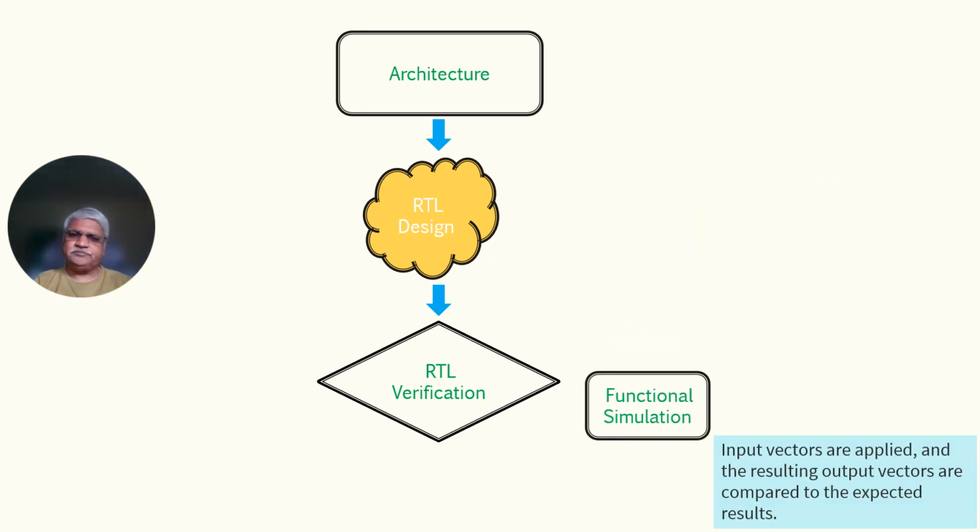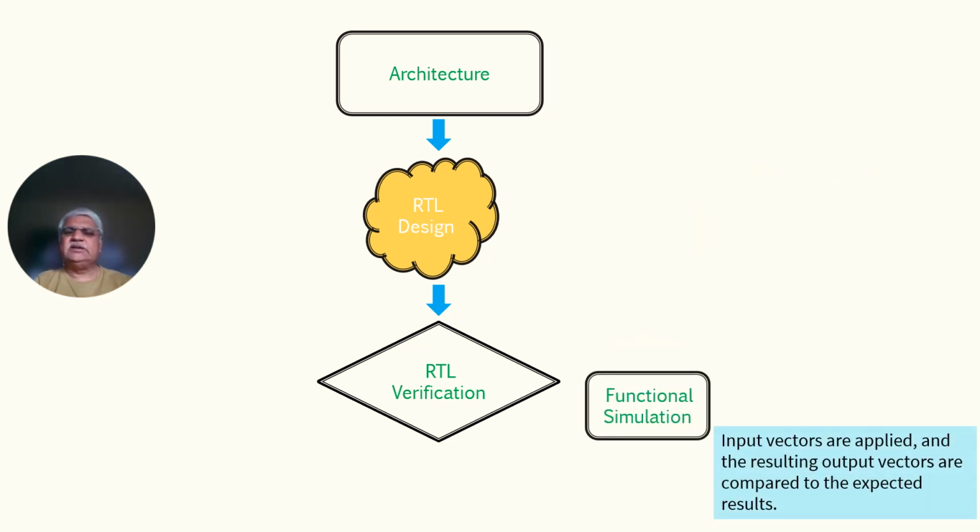If we understand this, then we will be able to implement the thing correctly through functional simulation. As part of the static verification, this is formal verification. There are EDA tools from Cadence, Synopsys, and Mentor, which model the expectations into mathematical algorithms and then evaluate the system for correctness.